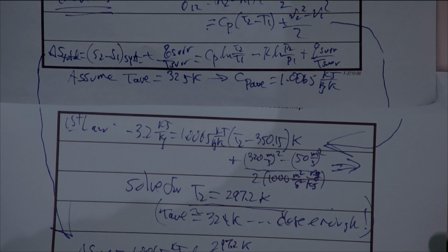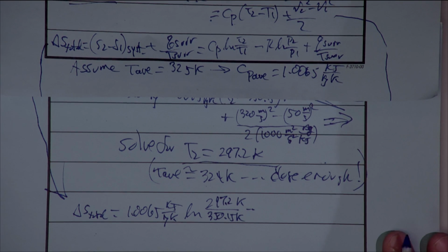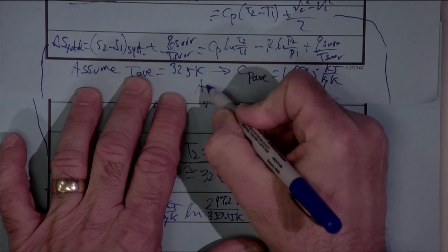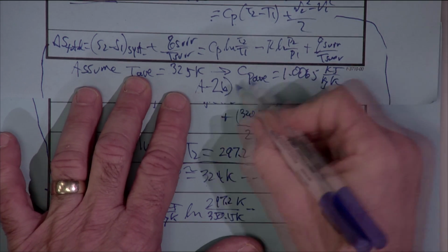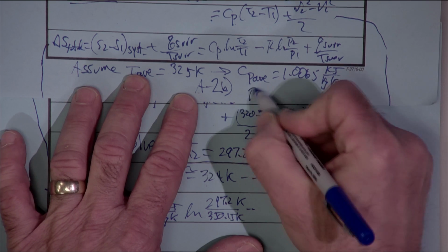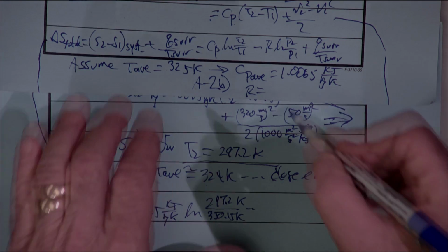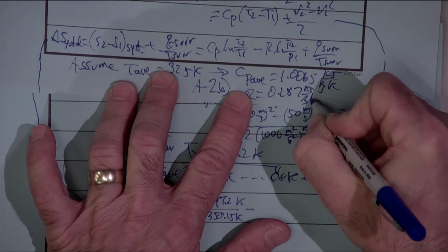And then we subtract from this R. Now, I probably should have gotten the value of R when I went back into the table just a minute ago to get my average value Cp. So maybe what you should do is note table A2 part B, that's going to be Cp. But also, from part A, I can find the value of R. For air, R is 0.287 kilojoules per kilogram per Kelvin.